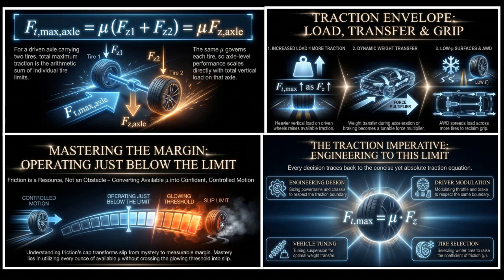The same equation guides both engineering and driving decisions. Ft max equals mu Fz. Engineers design vehicles around it, and drivers instinctively respect it through throttle and brake control.